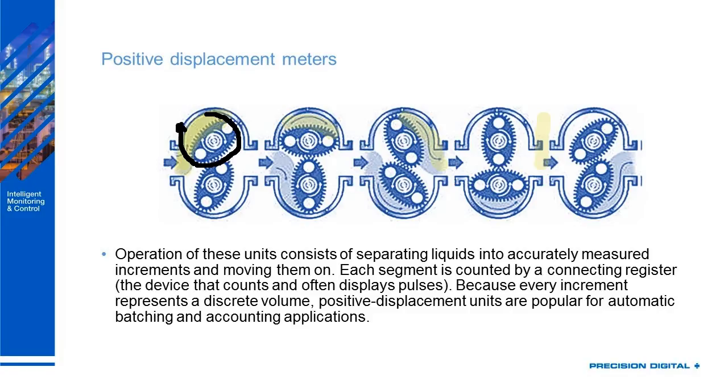Pulses are most easy to generate off of rotating equipment, usually by using magnetic pickups. So I can generate pulses as this gear spins, knowing that it's let through a specific discrete amount of liquid for that number of pulses that I managed to generate.